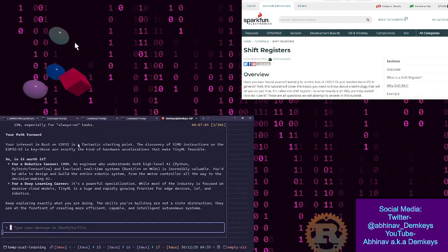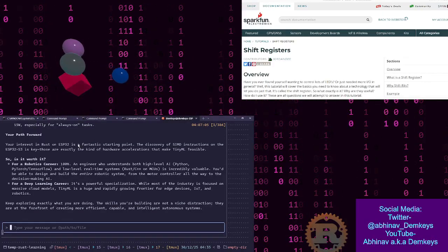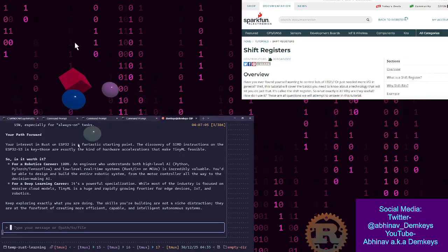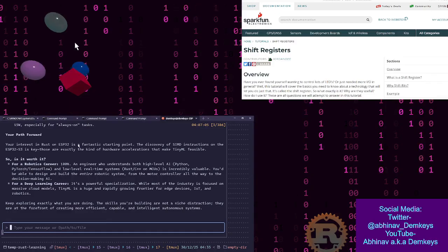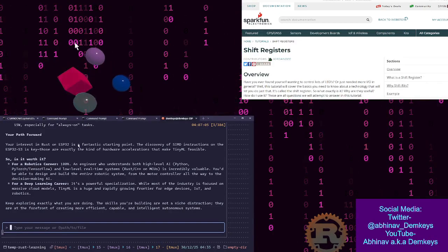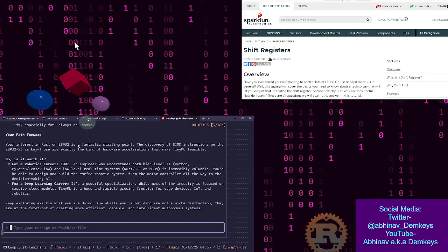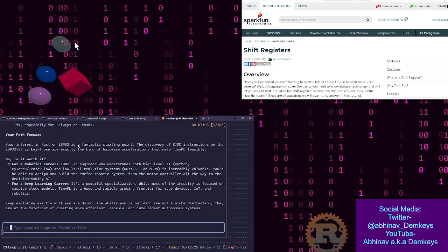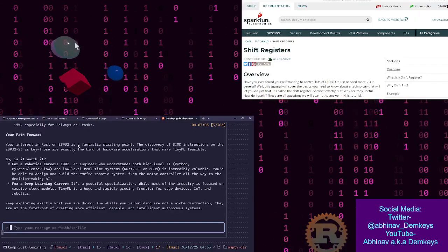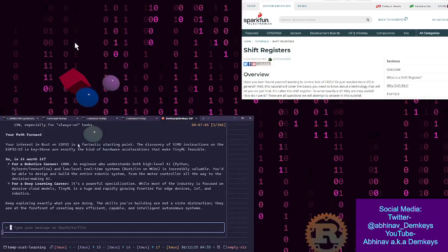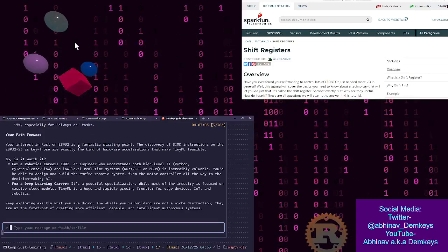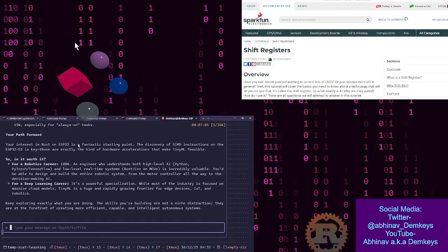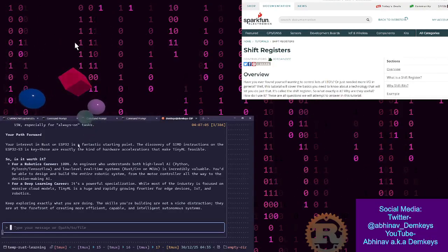The ESP32 generates a lot of heat itself, so it'll be harder to check the current temp. Oh, no, back up. Hold on. I'm looking for the ESP32's thing itself. Okay, so if we look at this temperature sensor, the ESP32 has a built-in sensor used to measure the chip's internal temperature. That's what I'm looking for.